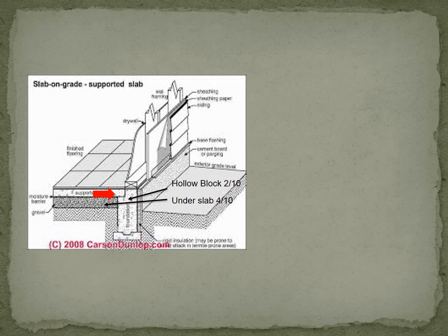Keep in mind, I did this for illustration purposes, showing 2 different drill spots, but you would actually just use that first drill spot, the hollow block one, and continue with your bit all the way under, and then treat the block, and then as well as put a longer rod on and treat all the way up under the slab. But this gives you an idea of how and why you can do a full treatment when you're dealing with a supported slab.